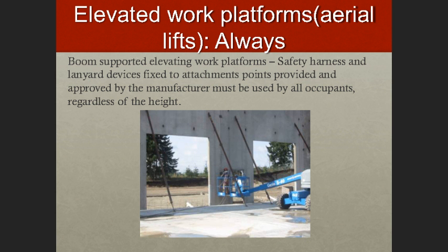Now this is tricky because not all manufacturers require that employees tie off in the man basket. It's not an OSHA regulation, but OSHA will look at the manufacturer's written recommendations, and if the manufacturer says that employees should be tied off inside the man basket, then OSHA will cite you under the general duty clause, the catch-all OSHA citation. So be aware of that and double check that.